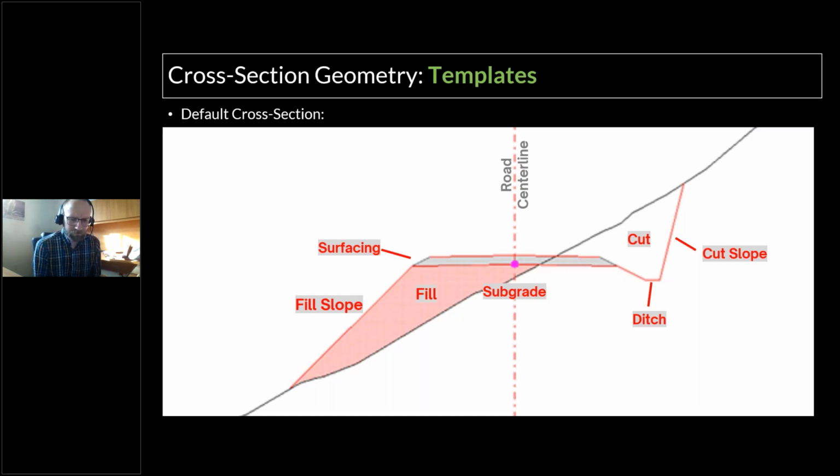One of the biggest differences between a geometric design software and a GIS or mapping software is that we're going to consider the road as a surface instead of a line. To do that, we take a line, the center line, which is a 3D line with curves on it, and we attach a cross section to it. As the center line moves, the cross section dynamically updates to show the geometry and the behavior that you'd like. That changing and dynamic behavior isn't trivial, so it takes logic to make them behave appropriately. Each cross-section template or template component is like a mini program.